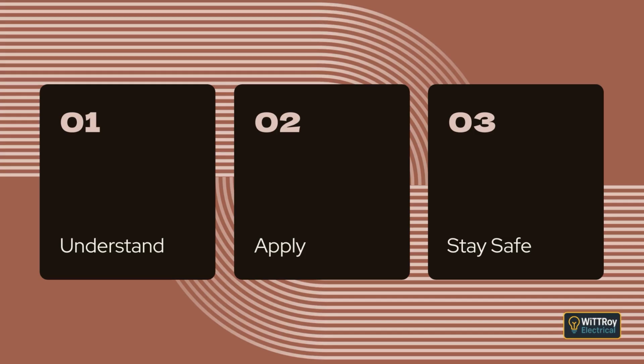Option C allows cases where overload protection at the main switchboard is considered enough, when the mains are installed in a way that limits the risk of overtemperature. In this case, short-circuit protection may be supplied by equipment at the switchboard or by a service protective device. The key teaching point is that consumers' mains must always have effective short-circuit protection, and overload protection must be provided either at the origin or at the main switchboard, depending on the installation method.